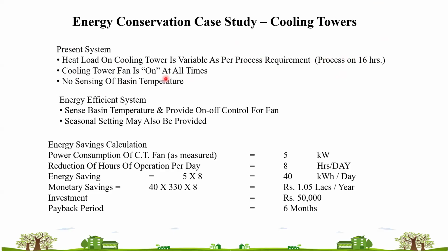No sensing of the fan, no sensing of basin temperature. So what happens if you are not having this? Your process is on for 16 hours and your cooling fan is on at all times, which means for 8 hours it is not giving output to the system.